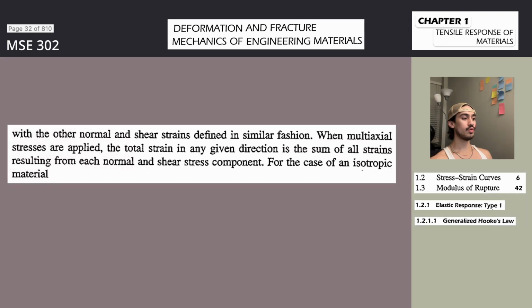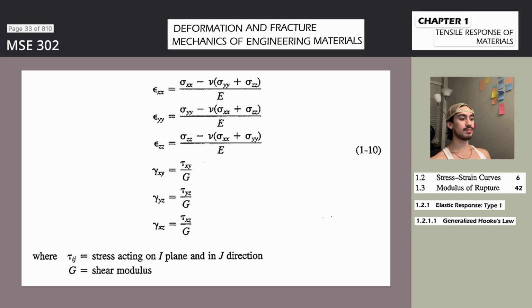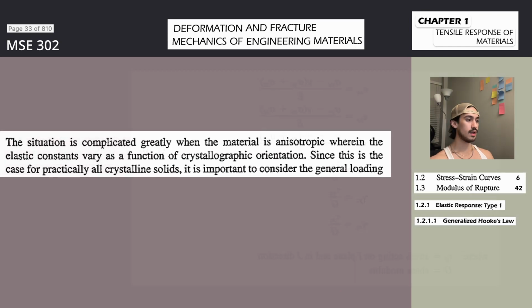The magnitude of the strain hardening coefficient reflects the ability of the material to resist further deformation, and may be equal to unity, which represents ideally elastic behavior, or equal to 0, which represents an ideally plastic material. Selected values of strain hardening coefficients for some engineering metal alloys are given in Table 1.5. Note that n values are sensitive to thermomechanical treatment. They are generally larger for materials in the annealed condition and smaller for the cold-worked state.